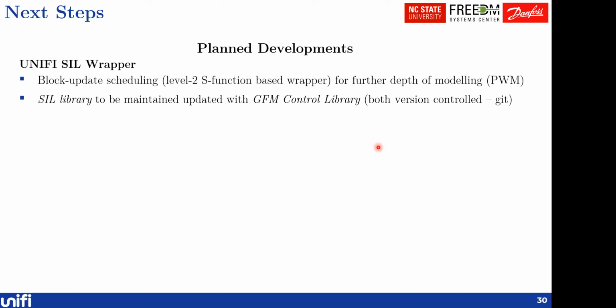That's what we do for our internal use, because in very high power applications, let's say 5 or 10 MW applications, in most cases when we're using IGBTs, the PWM update rate is not fixed. And to do that, we basically use a block scheduler, which uses a MATLAB S-function based environment.